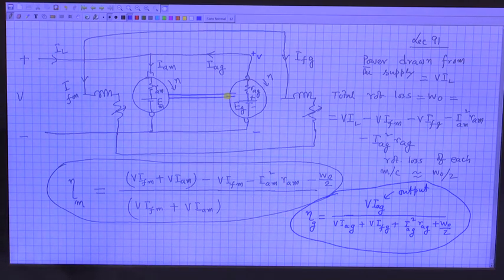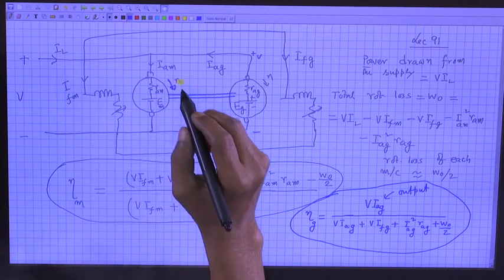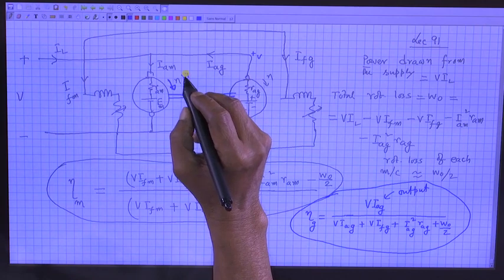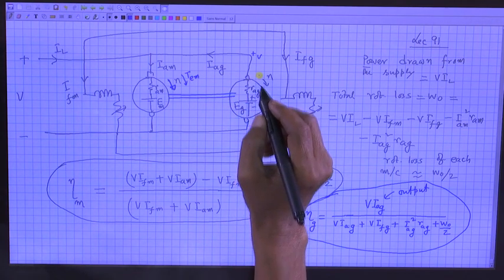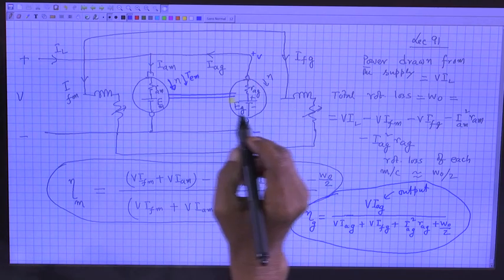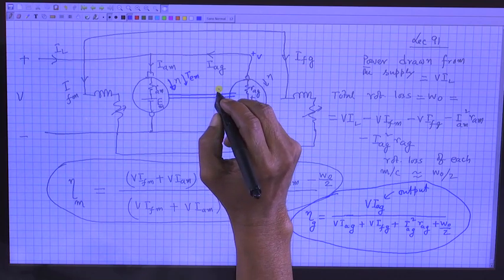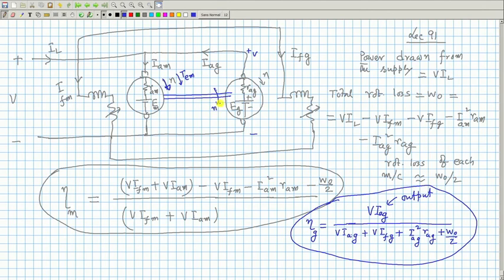Motor, this is speed N, and the electromagnetic torque developed by the machine will be in the same direction as that of the rotation. Similarly, generator direction of rotation is same, N, but the electromagnetic torque developed by the generator will be in the opposite direction, TEG.